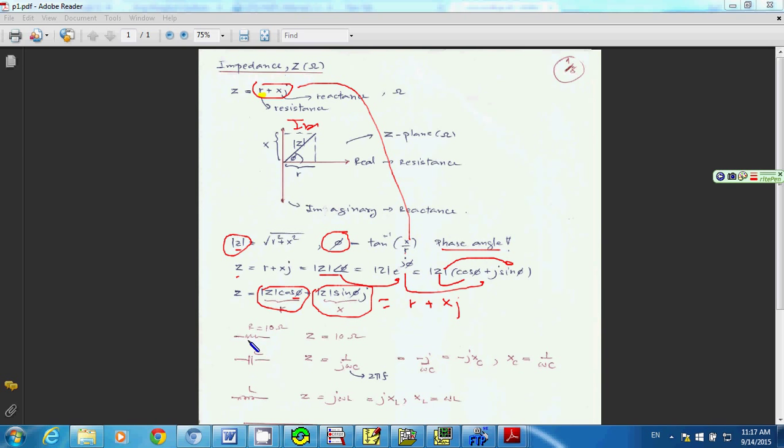So in general, when you have R resistance equal to 10 ohms, your impedance simply become the pure real number, 10 ohms. And for the complex number, or the pure imaginary part, you actually get it from capacitor and also inductors, because you know that the impedance of your capacitor equal to 1 over j omega C, when your omega is equal to 2 pi f.